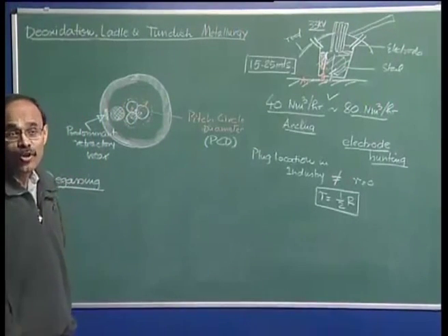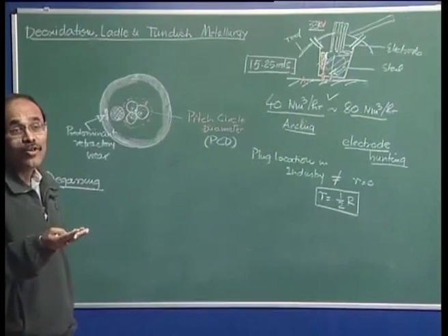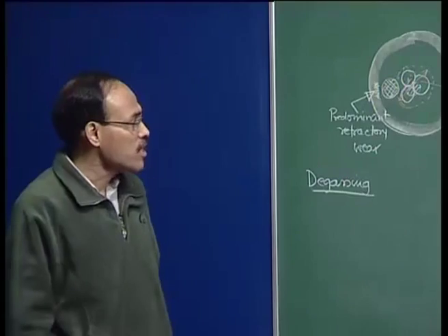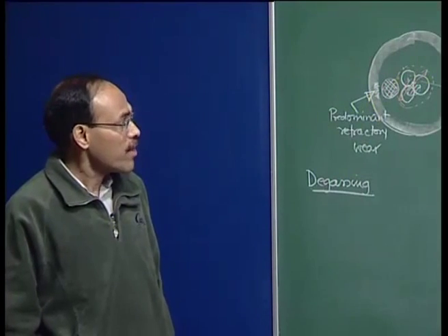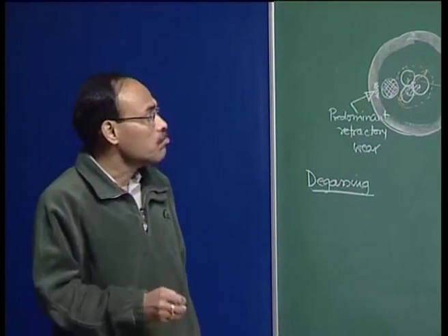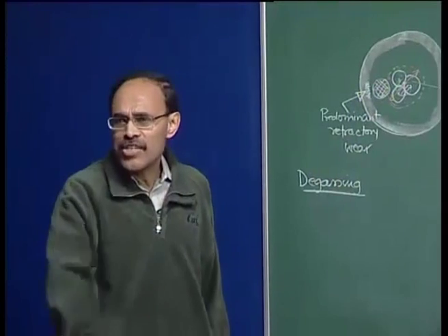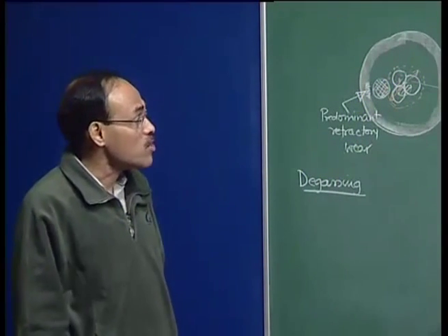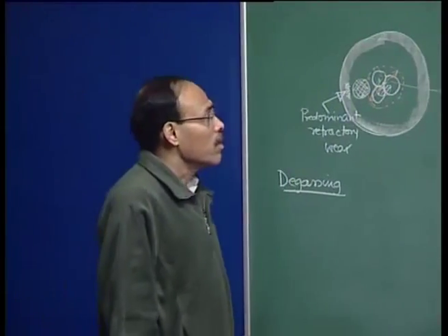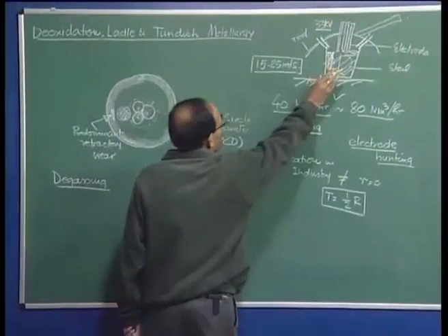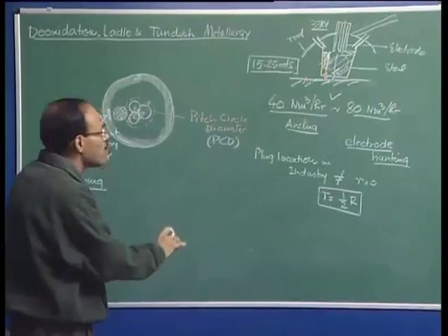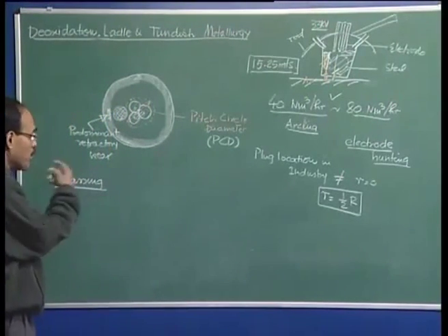We all know that hydrogen causes embrittlement, nitrogen impairs toughness of steel very drastically, and also if you are talking of making a deep drawing steel, in that case a significant amount of nitrogen is not tolerated. So, at this particular stage, even beyond the ladle furnace, we may have some nitrogen and hydrogen, which have to be eliminated.